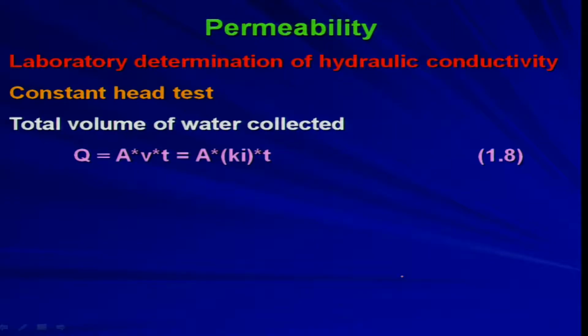The volume of water collected at time t is capital Q, which is nothing but A into v into t: the area of the soil specimen, into the velocity of the flow, and the time t. So, at time t, whatever water you are collecting.